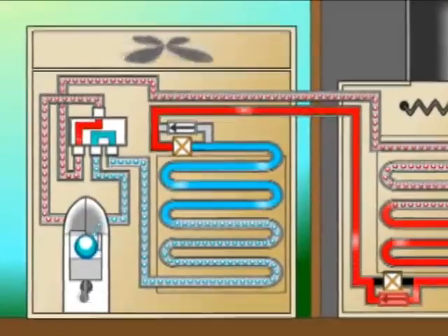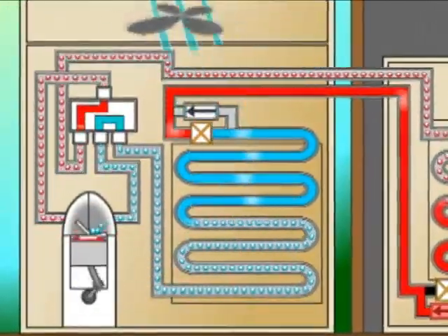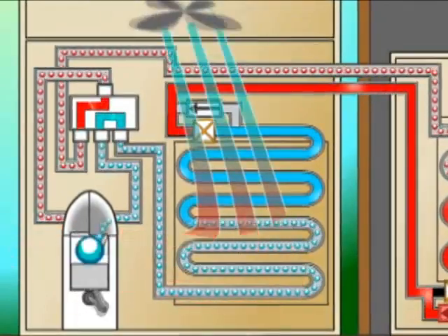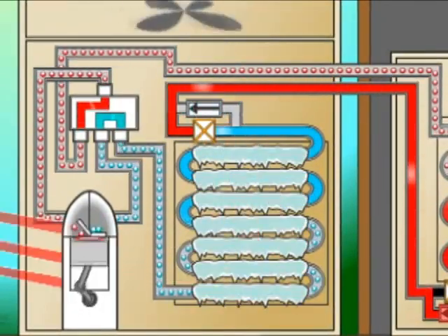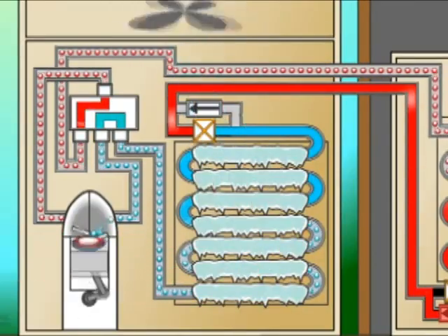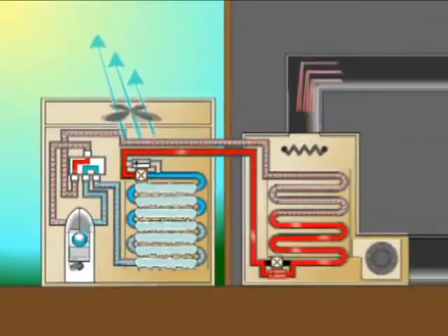There is one inherent problem, however. In order for the evaporator, now outside, to absorb heat, it must operate at temperatures lower than the outside air. This very low operating temperature allows ice or frost to accumulate on the outside of the evaporator. The remedy? The defrost cycle.